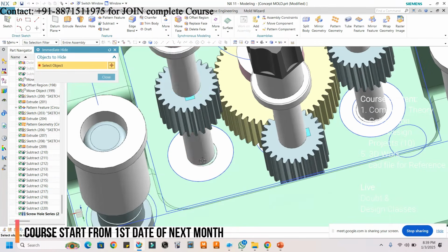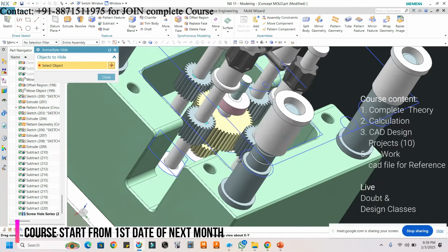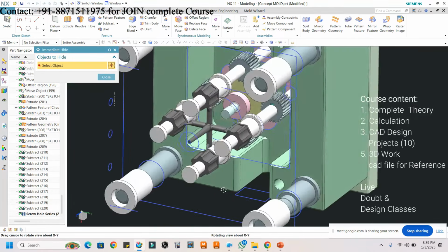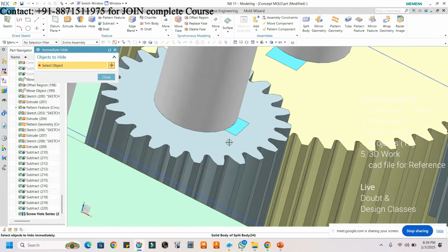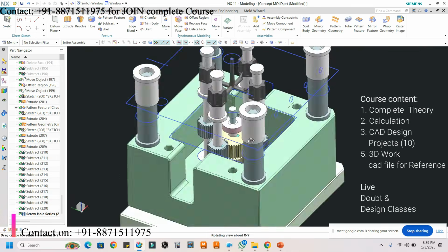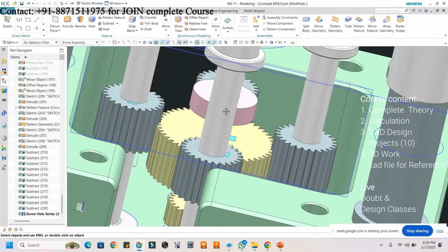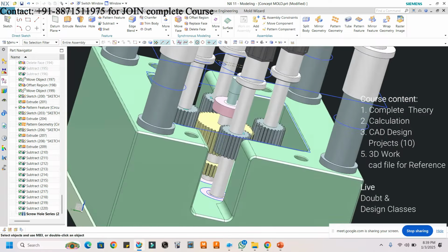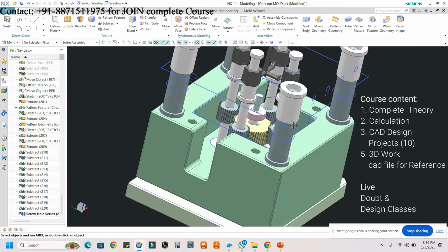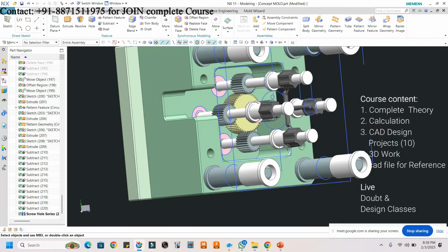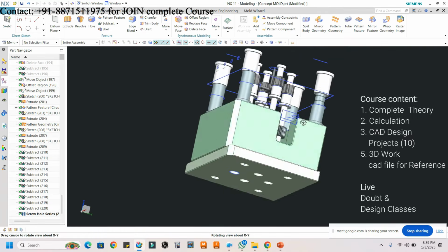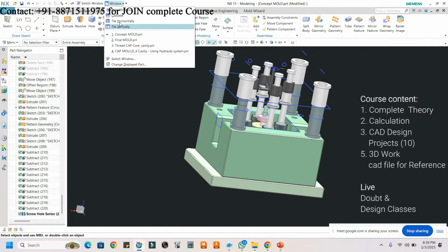Here you can see that the shaft location is wrong. How will we operate this pinion gear? Not possible. These are all the keys and everything, but this is not the proper way. Here we are using only one bearing for the center gear, the center shaft only. But a bearing is required for this portion also, for the planet gears also, for smooth operation. Right or wrong? Yes, sir. Okay, understood? Okay, so here, one minute.